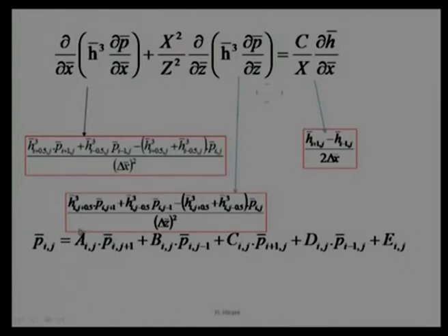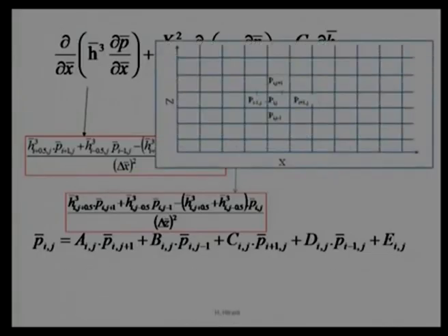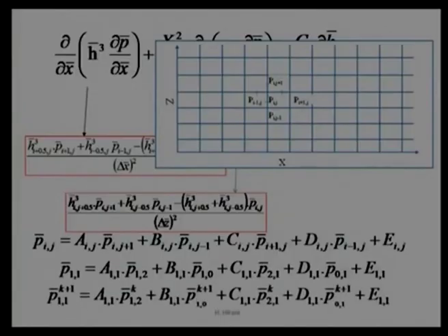Other multiplication factors with all these pressure terms will remain constant at any one node; they will not change. However, the pressure will continuously change as per the iterations. It may increase if we use the initial pressure as 0, as gauge pressure is 0, or the pressure is atmospheric pressure. Then we will slowly get more and more pressure at the node, and finally it will reach a saturation limit, and that saturation limit we name the convergence limit. That was indicated in a previous lecture and is repeated over here.